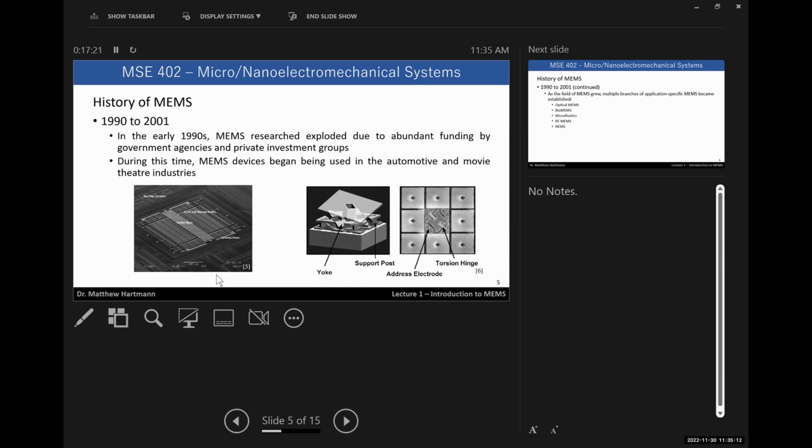Okay, so an accelerometer is a simple second order harmonic oscillator containing a mass, a spring, and a damper. So we have this large proof mass in the middle. We have springs here on this side and a set of springs over here on this side, where these springs are literally nothing more than silicon beams, which are able to deflect in pretty much a single direction because of the orientation of things. And then all of this stuff on either side of the proof mass is a ton of parallel plate capacitors. Depending on how that proof mass moved, or the amount of deflection of these springs, it would cause a change in capacitance, and measuring that change in capacitance told you what the change in acceleration was. Okay, so that's how a basic capacitive accelerometer works.